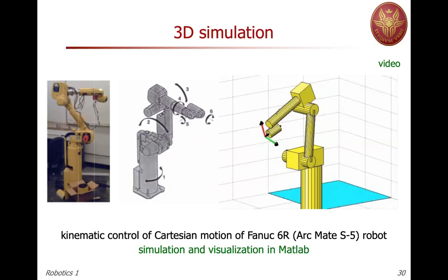So first of all, the path, I'm running this over and over. The path is really a linear path joining the initial position to the final position. So probably I have planned a motion going in a straight line there, and probably with a rotation for the end effector. Is this what happened? Why is the robot slowing down so embarrassingly at the end?